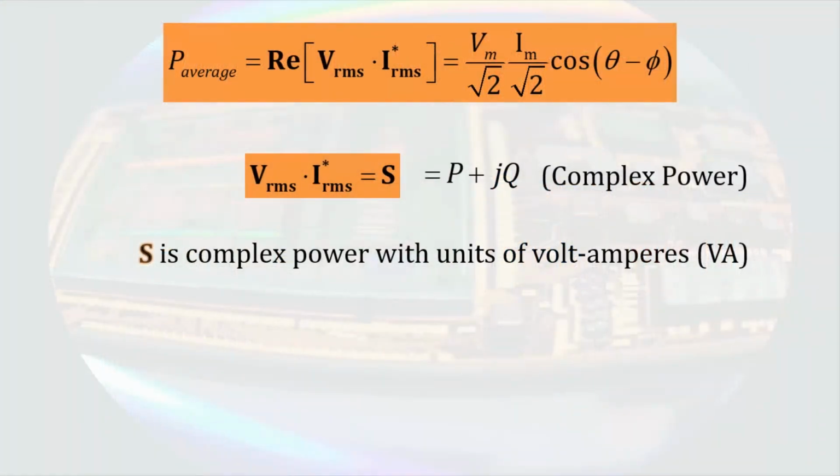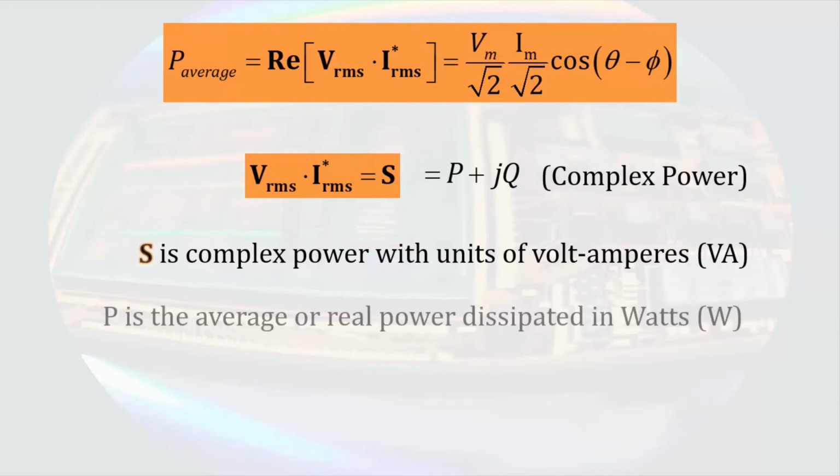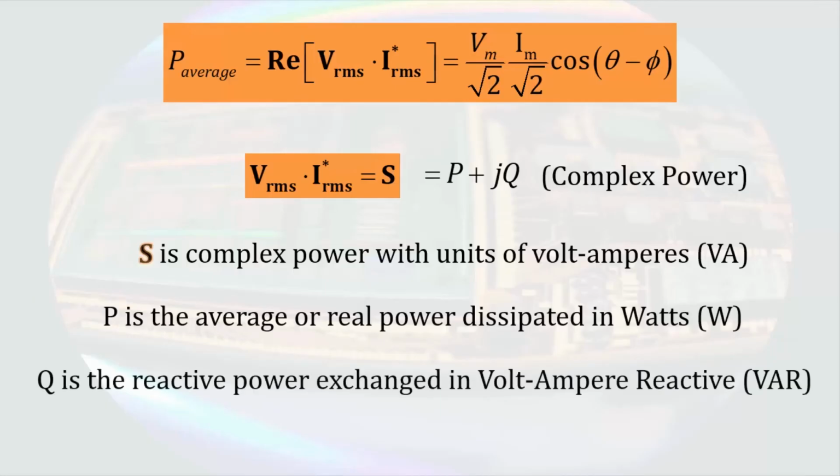So we have the complex power, the real power, and something we're going to call the reactive power. Mathematically, all of these have the same dimensions. However, to help our simple brains keep track of them, we refer to them with slightly different terms in units. Power is voltage times current. When our quantity is complex power, S, we use volt amps for the unit. P is the average real power, so we still use watts. Q is the reactive power, and this is measured in volt amps reactive.